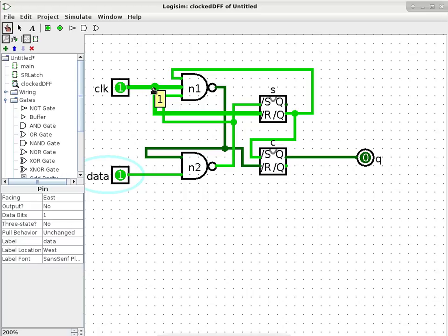The other place it goes is straight into /S of the SR latch. So that's going to do something because it's going to reset the Q of the SR latch. But when you reset Q, then /Q is going to be a 1, which means this wire will still maintain to be a 1. So in that case, C as an SR latch is going to see both inputs being a 1, which means do not make any changes, maintain your current state. Is that making any sense?